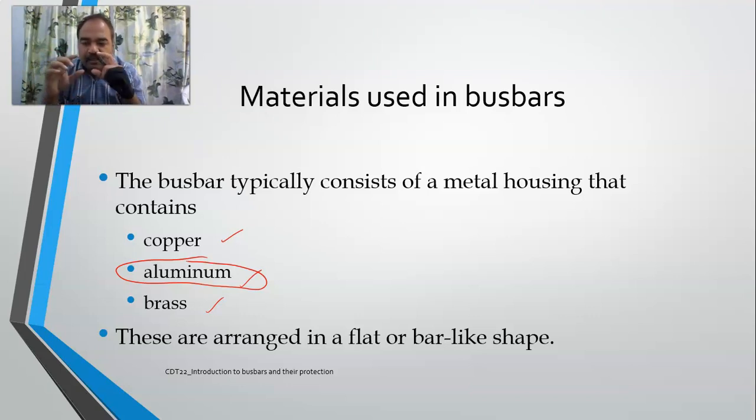So what will I do? I will join them to a copper bar. I will connect the 50 outgoing wires at 50 points, and connect the incoming wire as well. It is just like a physical joint of wires, a professional joining of wires, which obeys KCL: the sum of incoming currents is equal to the sum of outgoing currents.